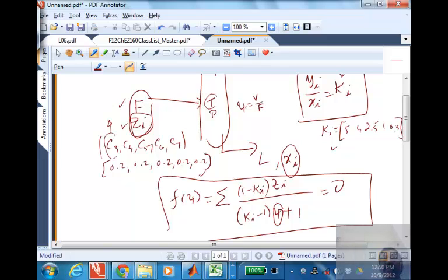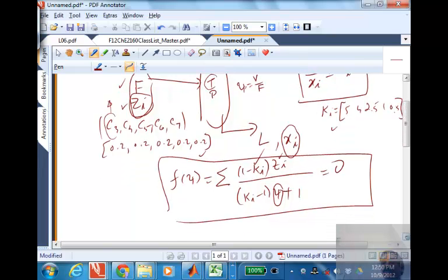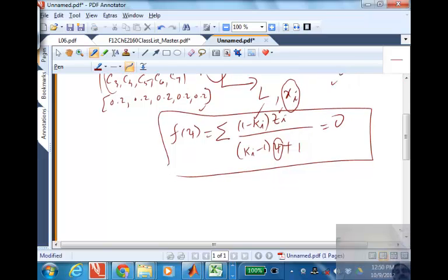In this equation, k is all known and z is all known. These are two sets of numbers that you must be given: what is the feed composition, and what are the equilibrium ratios, coming from experiments or from a thermodynamic model. So you need to find that value of psi that makes that function equal to 0. Okay? What does that mean? Solve that equation for psi. In this particular case, it's a highly nonlinear equation, so we cannot really separate psi out and push everything else to the right-hand side to get an analytical result. So you must solve it numerically. Okay? And MATLAB has tools for solving equations of this type, a single equation which is a function of a single variable.